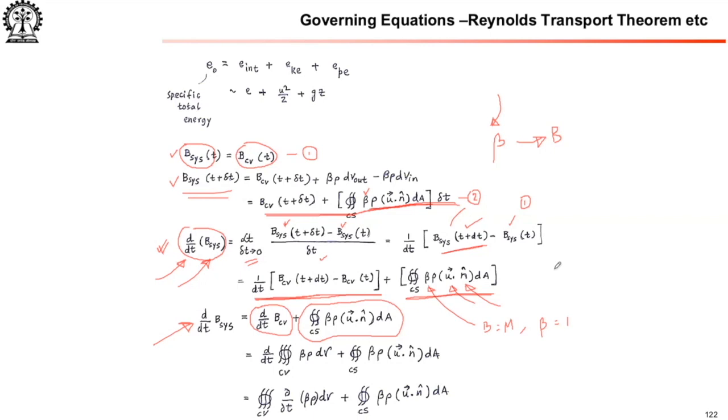We said it's a Lagrangian element, although infinitesimal, and we said the change of momentum of that element as it moves through the flow domain is related to the forces on it. We did the free body diagram, drew the pressure that creates the normal forces, and did the stress tensor, the tau xx, tau xy, and all those things. So it's almost the same thing.